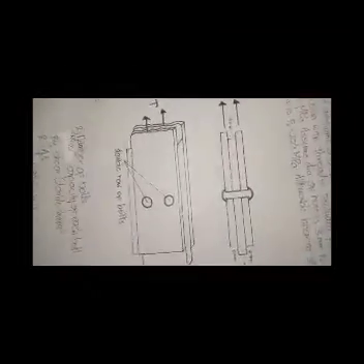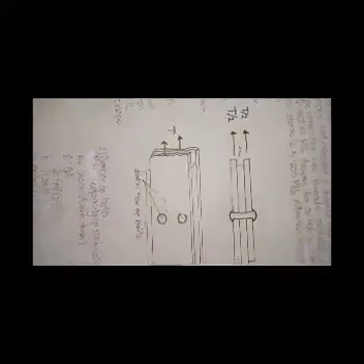So the center plate only is the one we consider, which is 9 mm thick that we will use. And solve for A sub g or gross area. Then A sub n or net area is equal to 150 minus 22 times 2 times 9. The answer is 954 mm squared.